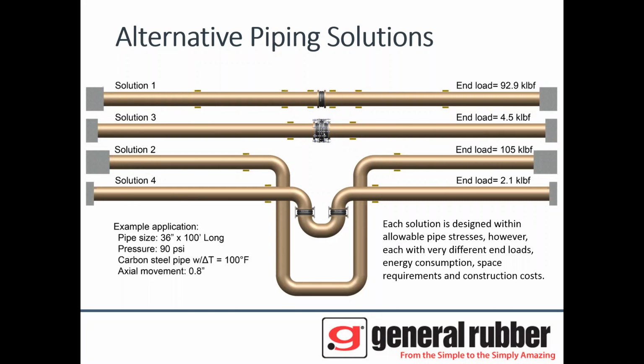Sometimes the support structure and adjacent equipment cannot handle either one of solution 1 or solution 2's forces, even though the piping is within allowable stress. So solutions 3 and 4 come into play, where you can directly absorb the axial movement and hold back the pressure thrust force with an inline pressure balance joint, and the end loads become 4,500 pounds, or you put a much smaller flexible U with 2 universal joints, and that has an end load of a little over 2,000 pounds.